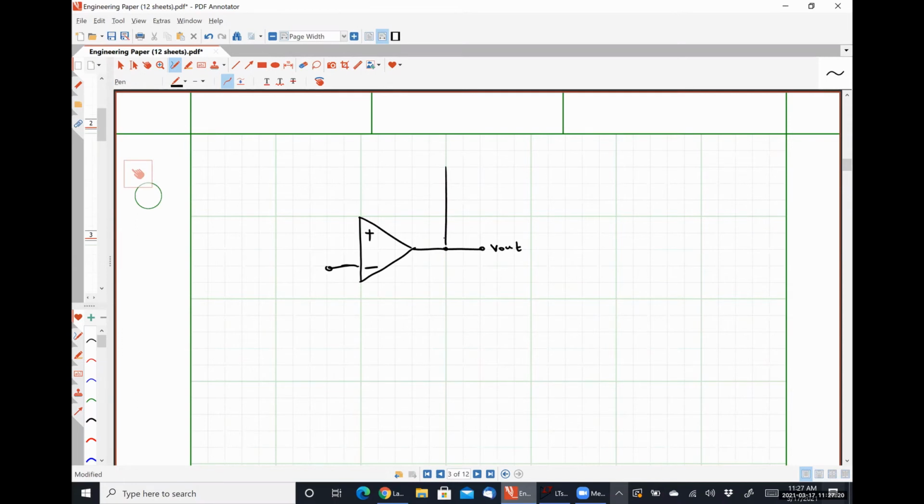So we're still going to have our positive feedback. Here's resistor R2, VCC plus, VCC minus. Here's our resistor R1. And now we are going to place Vref at that leg of resistor R1, and we're going to apply Vin directly to our inverting input terminal.